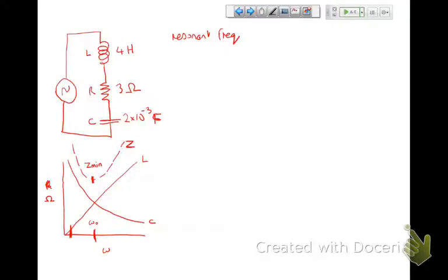And if I go to a frequency that's above my natural frequency, I still receive that input, but the current that it generates within me is so small at that frequency that it doesn't do much for me. And if I go to the natural frequency, although there is some resistance, it's the lowest resistance possible for this circuit. It's equal to the resistor's resistance. And so I get my maximum current flow, which means that my speaker gets enough energy to actually make sounds that go into the room.